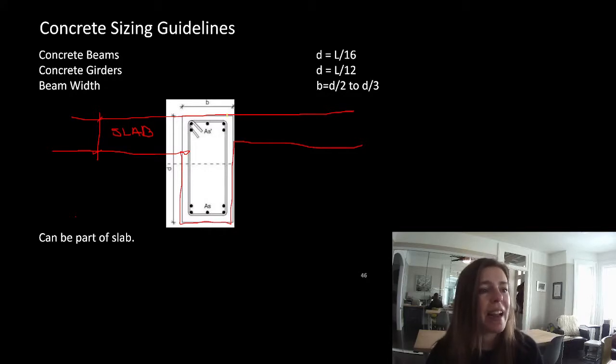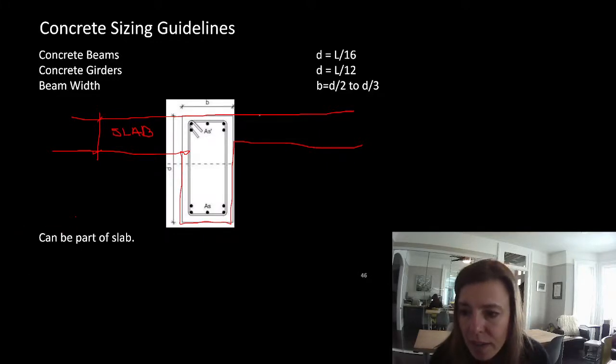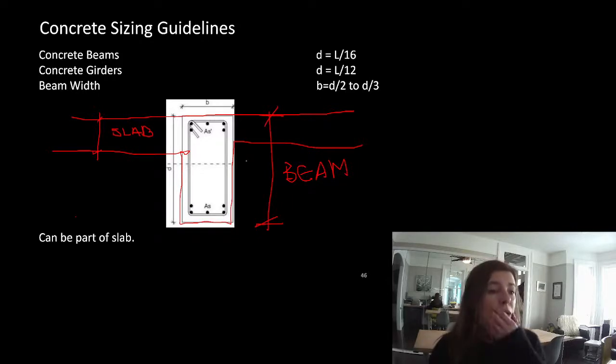You can see that the tops are aligned. So we've pushed that beam up into the slab. The beam depth is still from here to here. Actually, I'm going to draw that. So that's the beam depth. So we've superimposed them in on each other. Because you can run the rebar through each other, that's a really fun advantage that you can get with those.